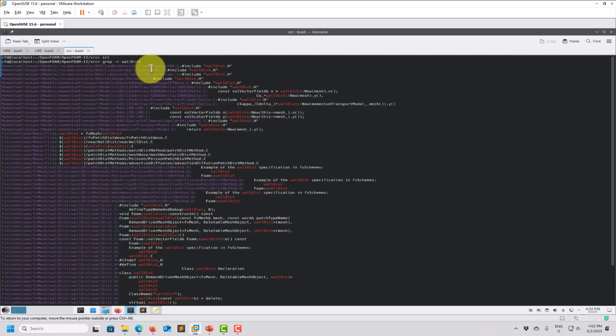So you can see that the K epsilon, the Lien-Leschziner, the Lien cubic, and the KKL omega, which is a transitional one, need that value. All the K omega SST needs that value, so it will be SST, SAS, and the transitional one. In the same way, the DES models based on the K omega SST will require that value. And curiously, I didn't know this one, the Reynolds stress models require that value. I have to check that one, but at least it is there, or this one, the LRR requires that value. And then you have the Spalart-Allmaras.